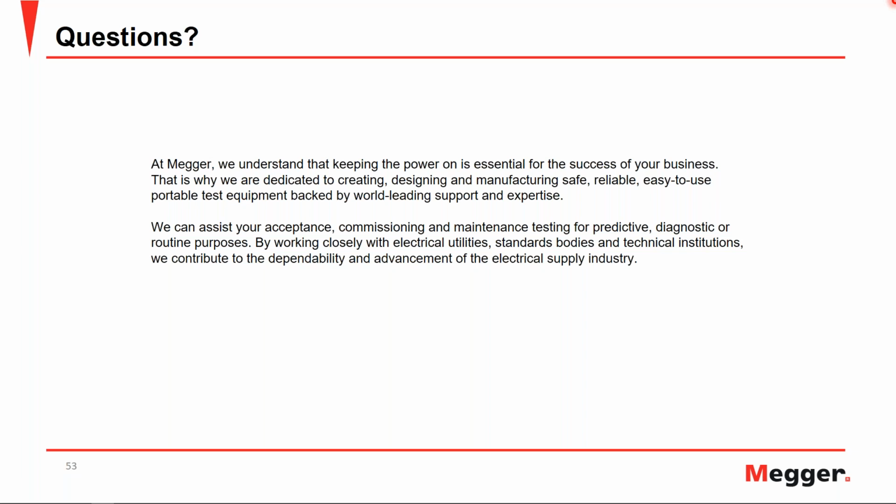So the ground cable must be placed on the test specimen ground, and all the grounds must be common. It is important to remember that the ground for the control unit must be the same as the ground of the high voltage unit, and then attached to the ground or the chassis of the transformer as well, or the test specimen. Otherwise, that light that we saw, the LED that indicates the open ground, will be illuminated, and only once you have a common ground will that light turn off and allow you to perform the tests.